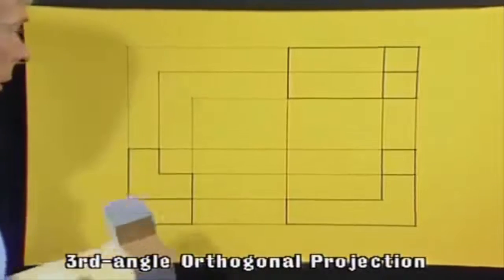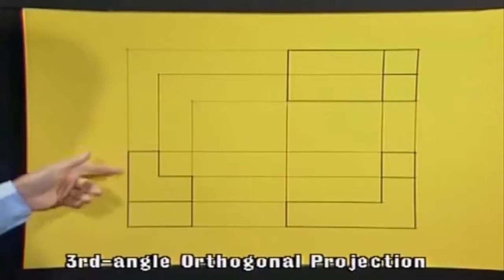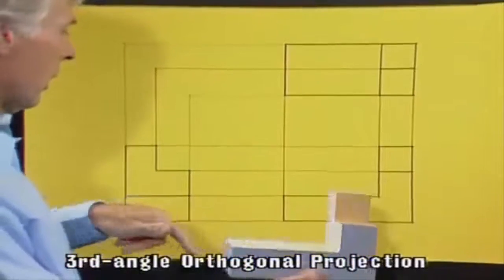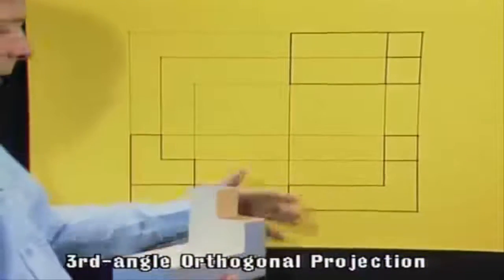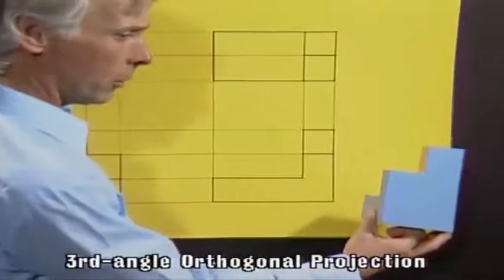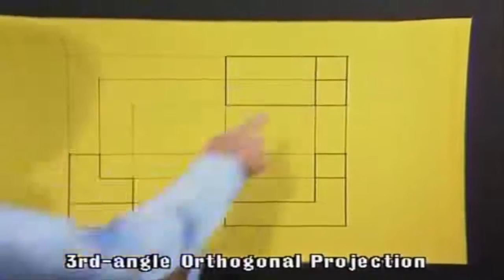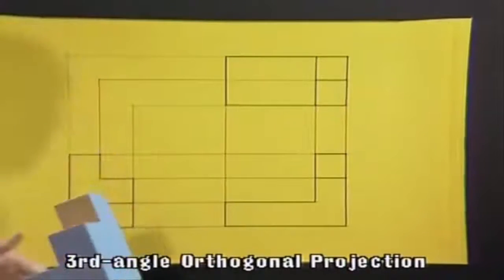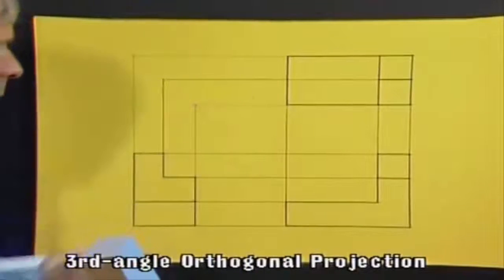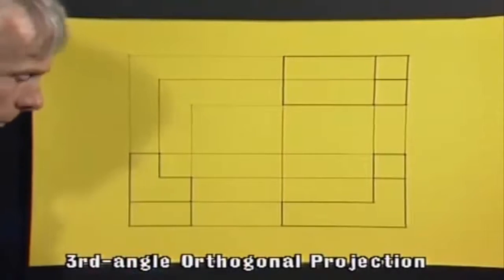There are in fact 3 views that are all that's actually required to fully depict this object so that it can be manufactured. I've got the front elevation. I've shown the view from the left-hand side in this particular case because it shows a little bit more detail than a view from the right-hand side. I've also shown the top view because it shows this detail. If you remember, the bottom view was just a pure rectangle. If that was dimensioned, that would be adequate for the component to be manufactured.